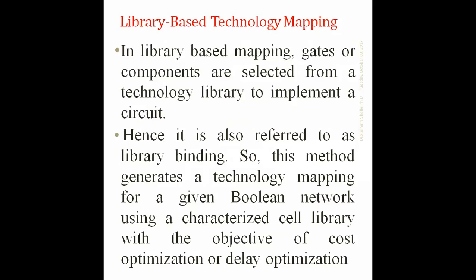Say I have to define a full adder. For the full adder, I need 2 XOR gates and 3 NAND gates, 5 gates in total. I already have a defined NAND gate function and XOR, exclusive OR, function in the library. I have to extract those components and interconnect them to give the exact output of the full adder. Predefined operations, predefined components, predefined gates are already there in the library. Simply selecting from that library to implement a circuit is called library based technology mapping.